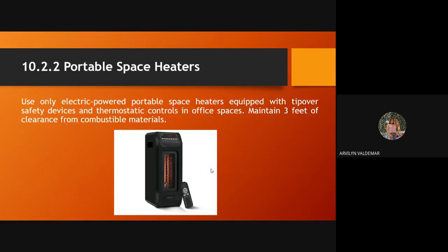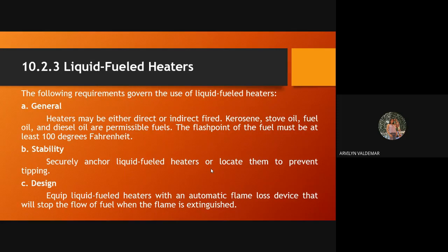So, portable space heaters. Use only electric-powered portable space heaters equipped with tip-over safety devices and thermostatic controls in office spaces. Maintain 3 feet of clearance from combustible materials. For liquid-fueled heaters, the following requirements govern the use of liquid fuel heaters.